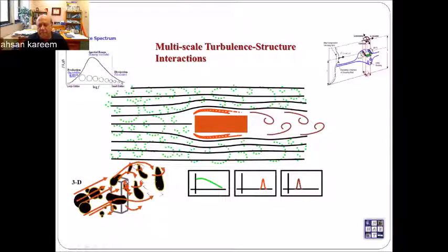If you look at a 3D view of a building, these globs are these eddies, which are coming, hugging your building, wrapping around it, twisting, tilting. So these are very complex nonlinear interactions, which finally result in buildings vibrating in the along-wind direction, across-wind and torsion, or in the case of low-rise buildings, we get tremendous pressures on the roofs of the buildings.